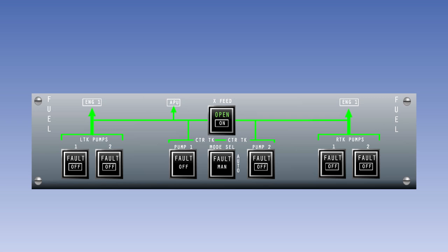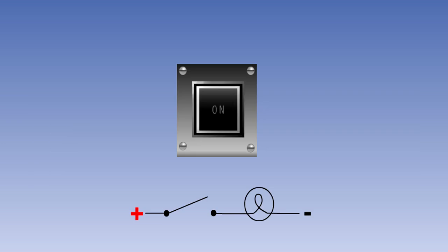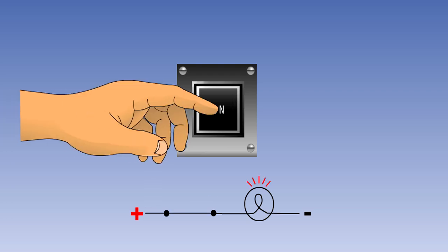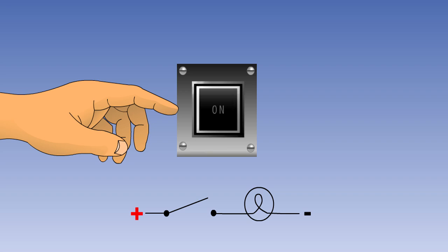Switch lights have largely replaced the other switch types in modern aircraft and combine the functions of a switch with the push action and an indicator light for the associated function. As with toggle switches, switch lights may be of the momentary action type, where the switch light is pressed and held to activate the service and released to deactivate it, or they may be of the alternate action type, where the switch light is pressed once to activate a service and pressed again to deactivate it.